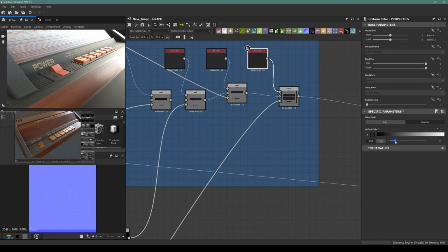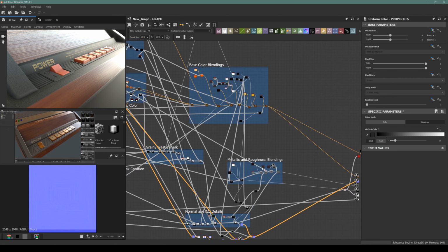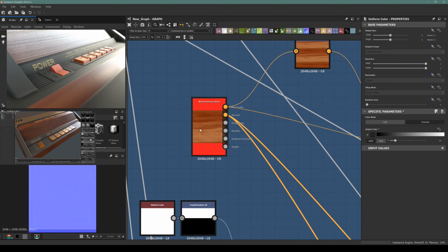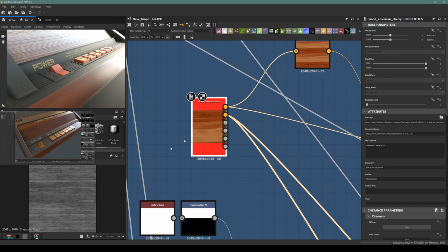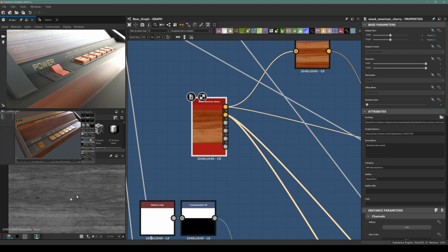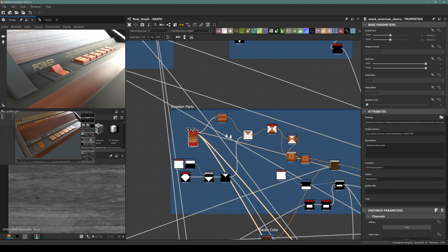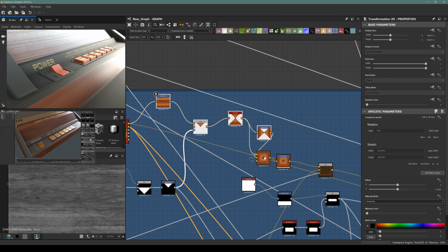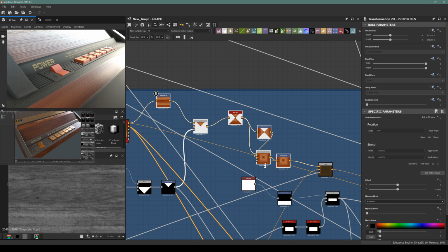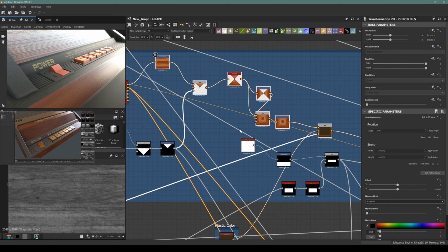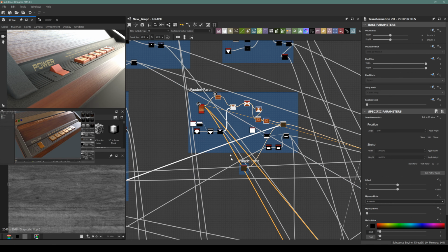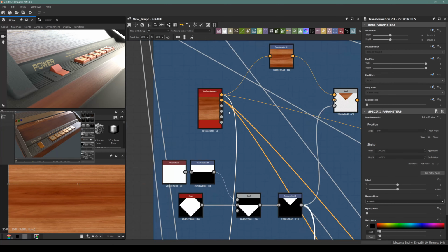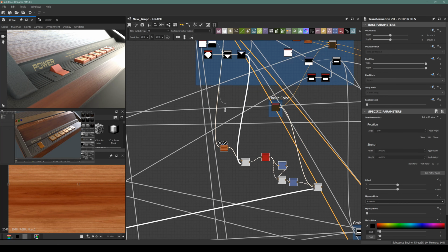So I can also adjust this as well, but also adding some roughness details from the material would be great. You see these details right here. So to do that, boring but the same thing, I will copy these nodes and then paste them here, and I will connect the roughness value here.